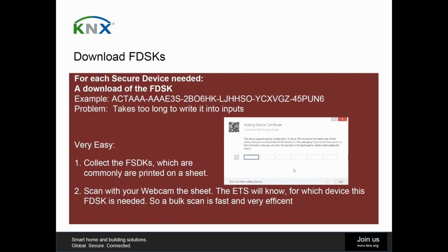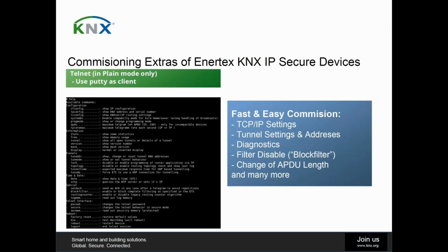A bulk scan is then very fast. And just to give you some overview about our Enertex devices, we have the possibility of using the Telnet client in plain mode only, just for security reasons. But in plain mode, it's very comfortable to change, for example, TCP/IP settings very directly, setting the tunneling addresses, and diagnostics.